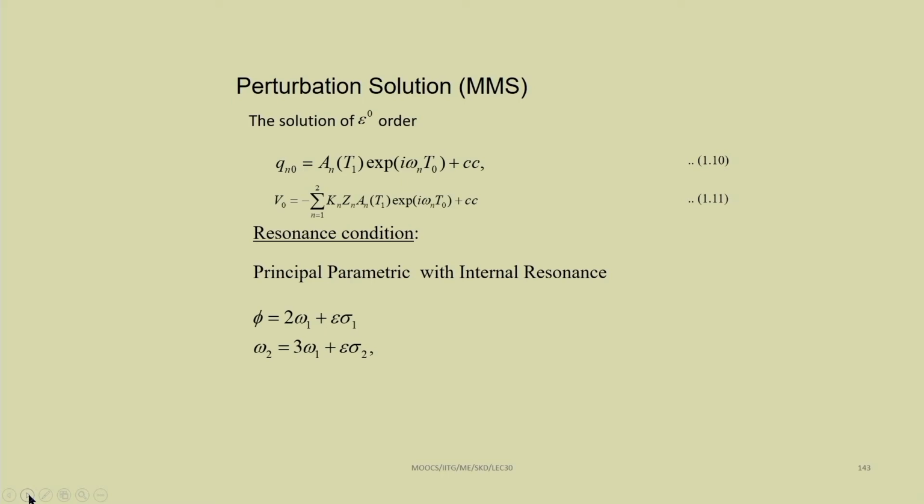So, one can find the response of the solution, particularly if you are using the Runge-Kutta fourth order, fifth order method. Then you can get the response of the system for a particular system parameter. For example, if one has to obtain the frequency response plot from the time response, one has to spend huge memory space and also time to get that simple frequency response plot.